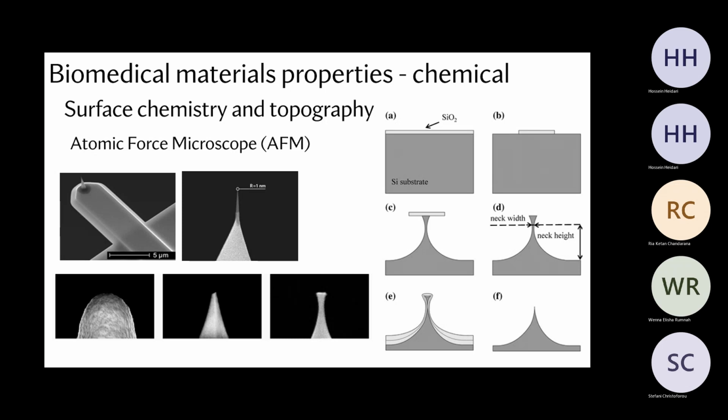So now they've patterned it there, okay? Then that silicon oxide is going to protect the substrate from the secondary etchant, which is going to now attack the substrate. And the etchant undercuts that layer. So if you give it too much time, it's going to try and go under. Okay?